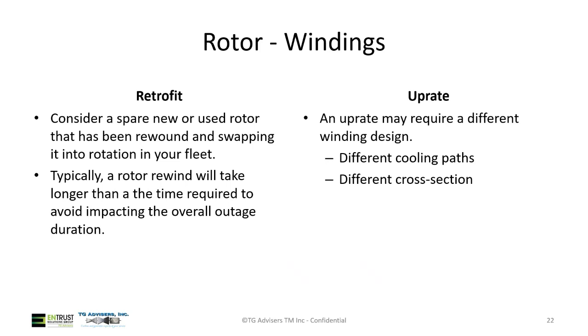For an uprate, basically the things you can change are your copper design, so your coolant paths, your cross section on your windings. And then I think the next slide I talk a little bit about the blower.